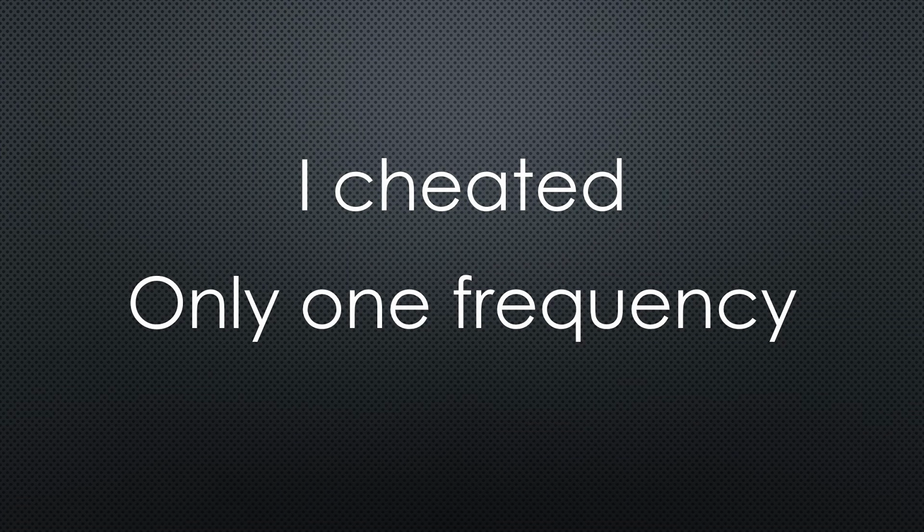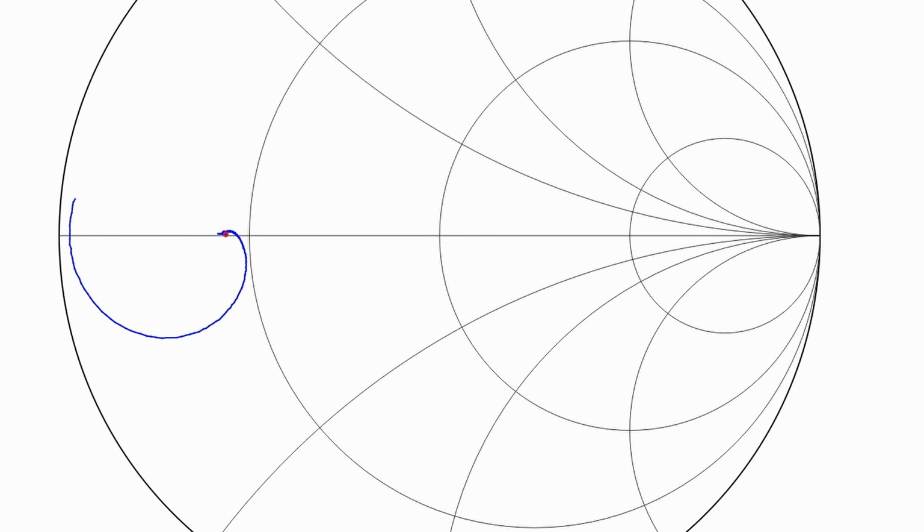I only used a frequency of around 10 MHz. If I change the range from 1 to 20 MHz, things become different. Suppose I leave the two parts where they were before, I now get a curve. Why is that? Capacitance and inductance change with frequency even if the part does not change.